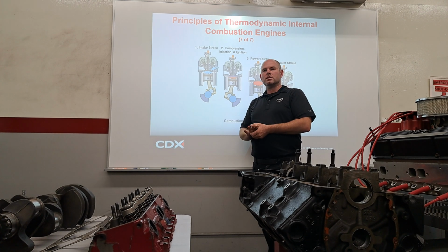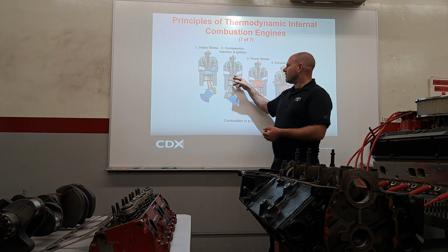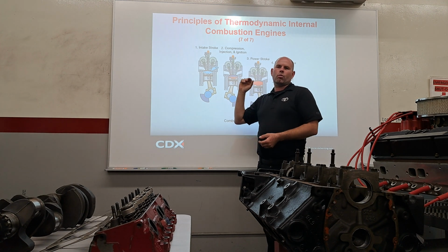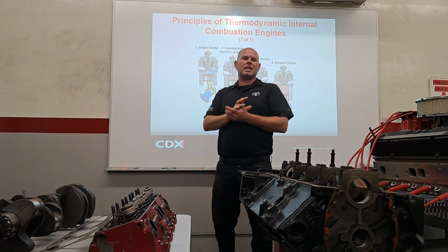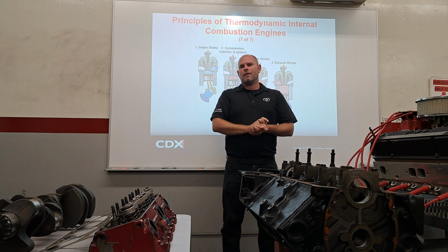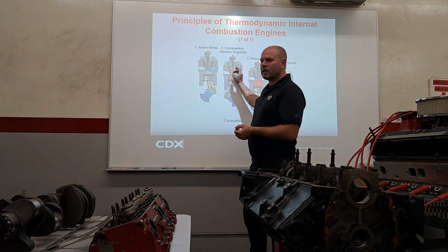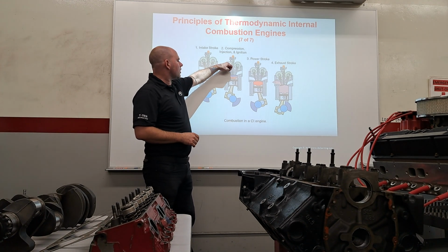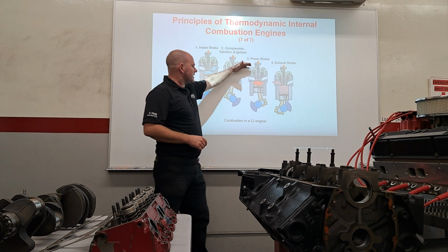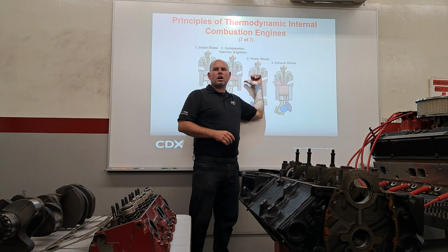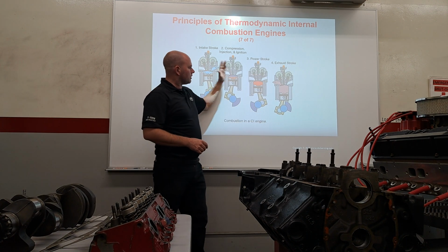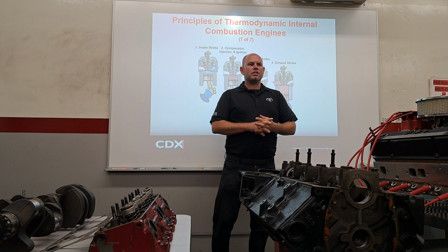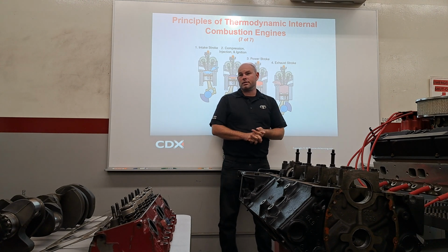The problem is, on a diesel, we have such high compression that gasoline wouldn't even be able to hold up to that 20 to 1 compression. Gasoline can't really handle those types of compression numbers. It's going to be out of control. Diesel's hard to ignite. It needs really high compression, but it's kind of stable in that way. Right? So we start the combustion with spraying the fuel, boom, and that's going to push it down. And then we still have to exhaust it. And then we start the intake again. So there's your 4 strokes on a diesel. Realistically, that's probably about all you'll ever need to know about a diesel, unless you change industries, which I'm not telling you to do.